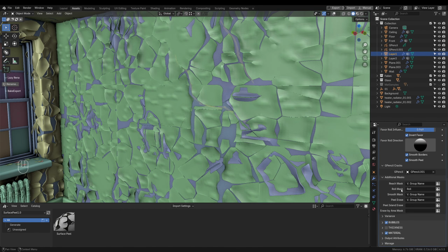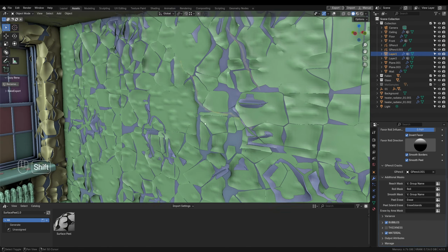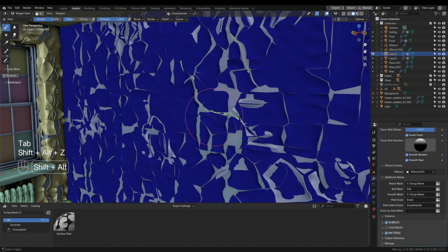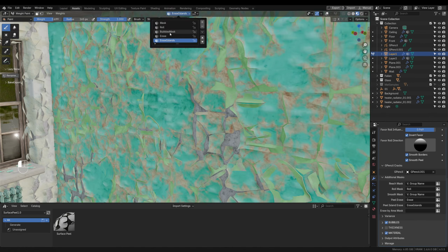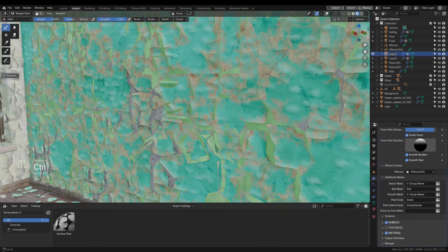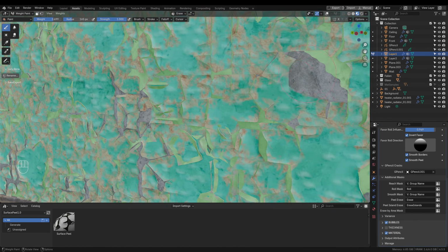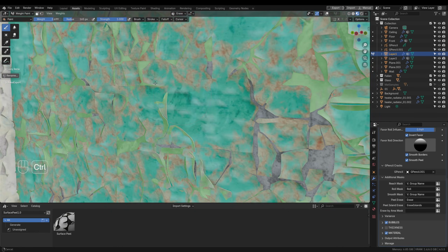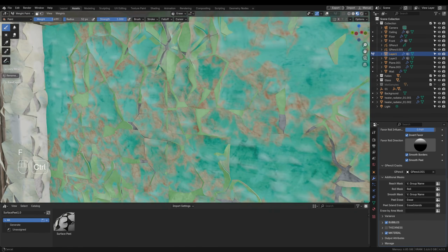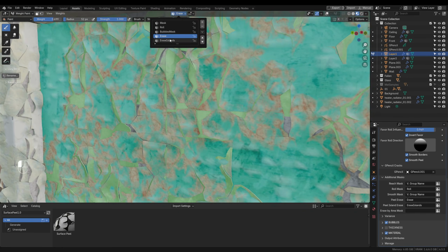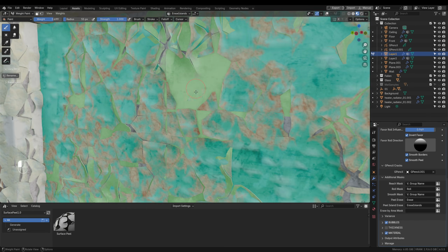So right now, if we plug those vertex groups over here in the modifier, now we can go into the weight paint mode. And first with the erase vertex group selected, let me show you how it works. So now where we paint with this vertex group on, the mesh underneath will be deleted. However, if we go for the peel islands erase with the other vertex group selected, you will see that if I paint even one vertex, the whole peel island will disappear.